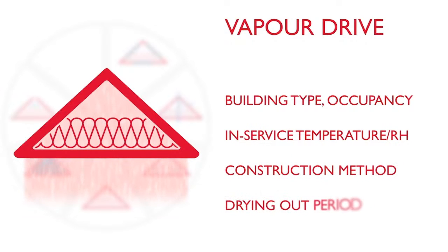Off-site construction such as timber frame or SIP buildings will also tend to have lower moisture loads, as there are fewer wet trades to dry out, and the building is usually wind and watertight earlier in the construction process. This construction moisture can lead to significantly higher condensation risks in the short term after completion. The vapour drive present determines the overall condensation risk that will be present, and as such is the start point of the hygrothermal assessment of the roof's performance.